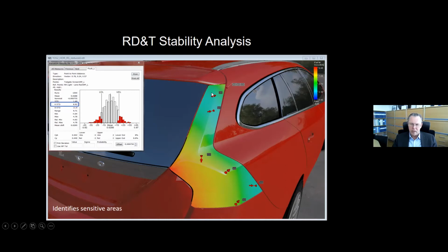So I have a contact between the lamp and the body in some points. There could be small pins or small planes and holes and so on. The red arrows are the symbols that describe where those contacts are. So if I put the contacts like this between the two parts, and I put the unit disturbance in all these points, I can see how that affects the geometry of this rear lamp.